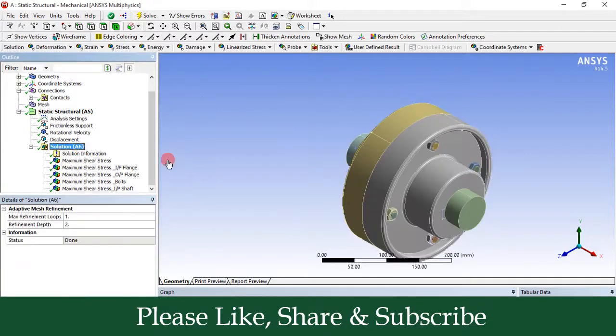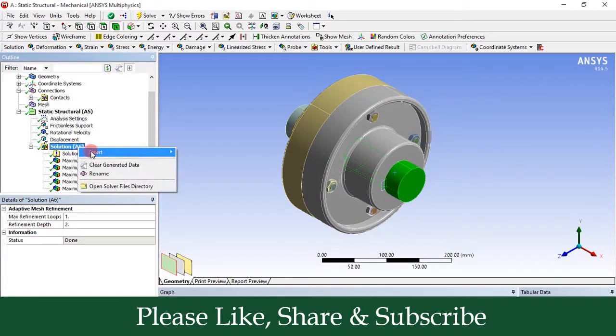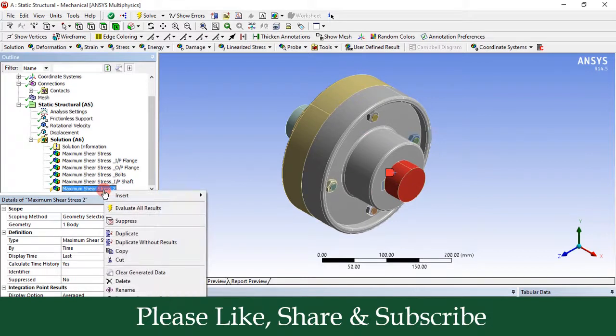Now let us select the output shaft for calculating the maximum shear stress in the output shaft. So go to the body button, select output shaft, then left click on solution, right click on solution, go to the insert, go to the stress, select the maximum shear stress. Then you can see here the output shaft is selected for this maximum shear stress parameter.